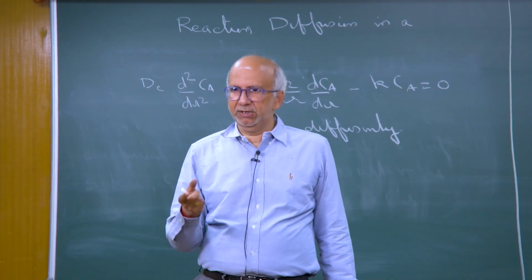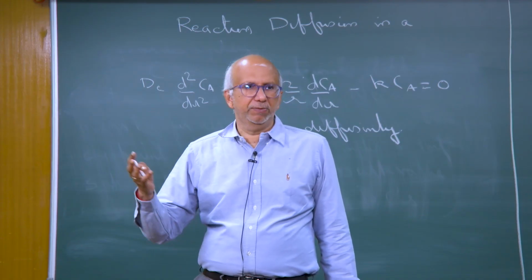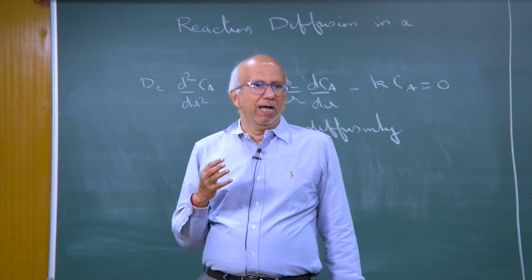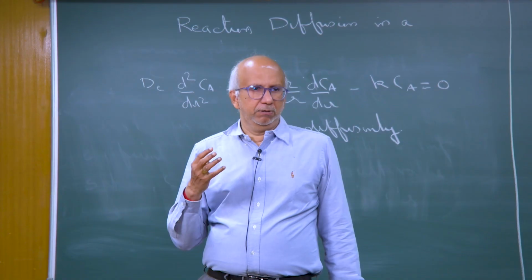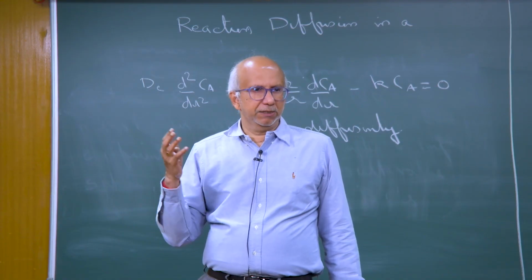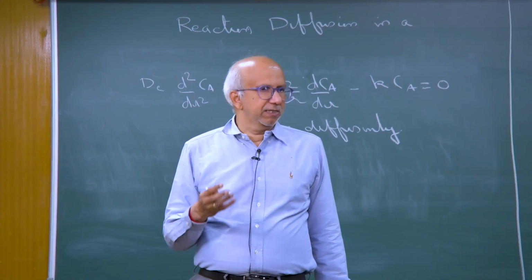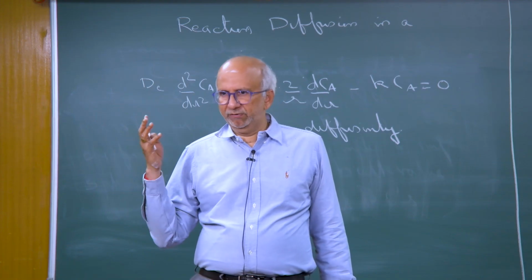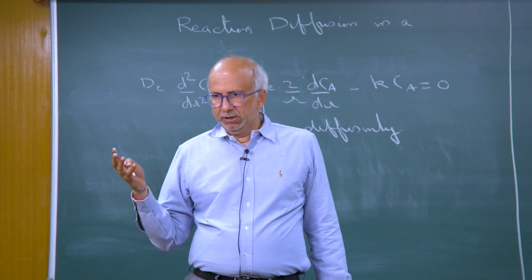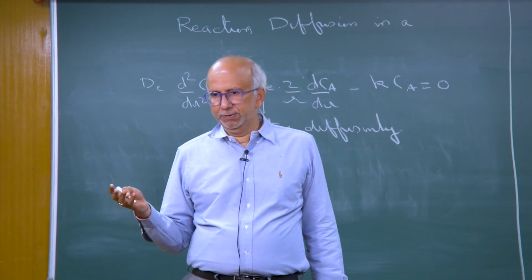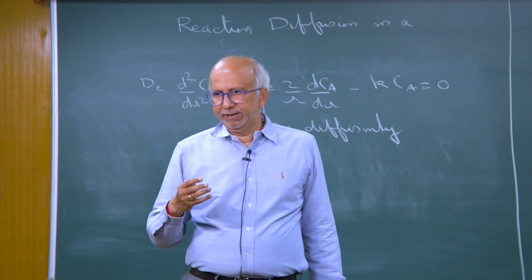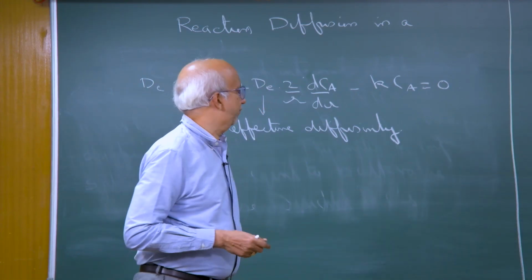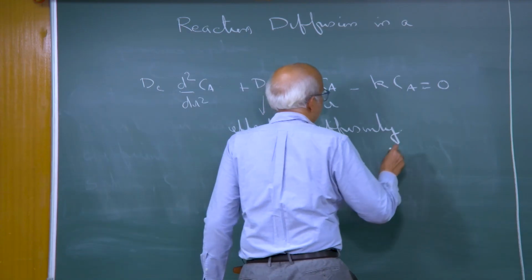So, some tortuosity will be there. So, it will be basically different from the traditional diffusivity. But we are just saying we can look at this mass transfer process as a diffusion process, and so it is not the actual diffusivity which you will have in bulk gas, when you talk about diffusion of benzene in air, you can use the same diffusion coefficient here. Okay. So, that has to be found experimentally, because this mass transfer occurs through a porous network. Okay.